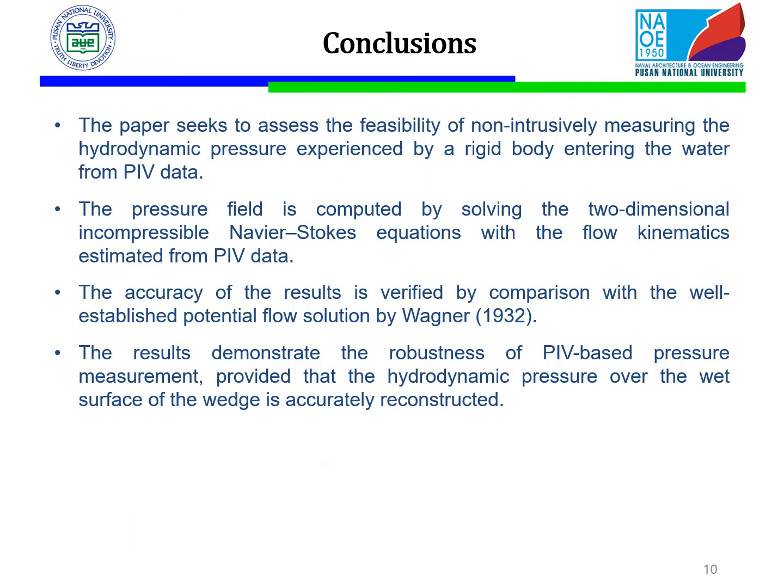In conclusion, this paper shows the feasibility of non-intrusively measuring the hydrodynamic pressure experienced by a rigid body entering the water from PIV data. The pressure field is computed by solving the two-dimensional incompressible Navier-Stokes equations with the flow kinematics estimated from the PIV data. The results demonstrate the robustness of the PIV-based pressure measurement, provided that the hydrodynamic pressure over the wet surface of the wedge is accurately reconstructed.